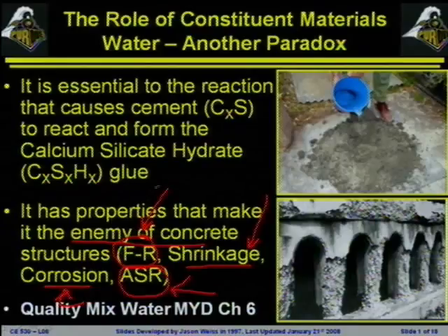So water is going to be both essential, but if we have too much water during mixing, it's going to be a problem because it's going to make our concrete porous. If we have too much water later on, it's going to lead to some other degradation problems.